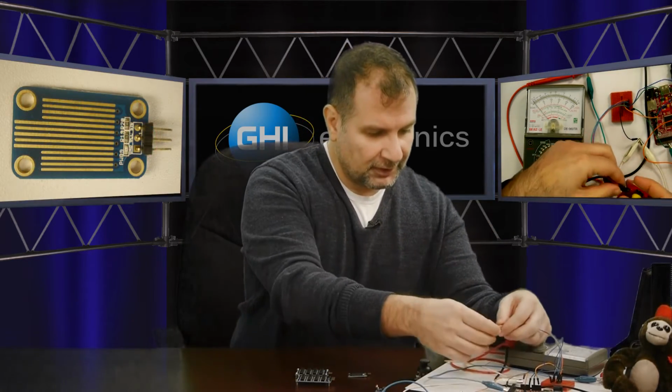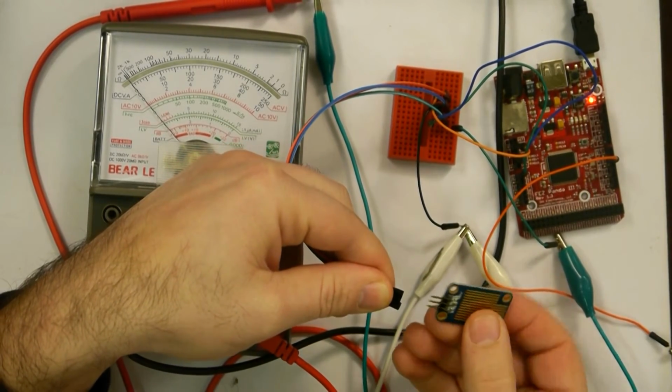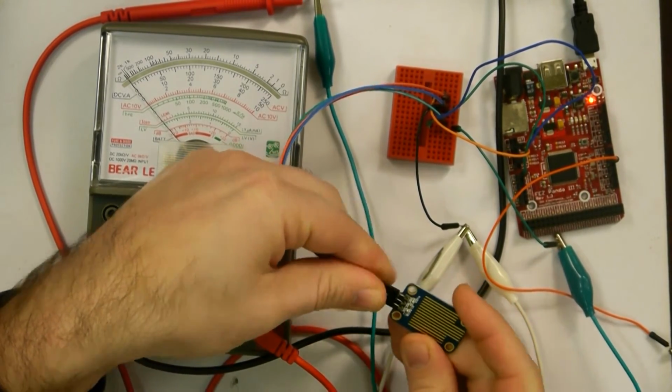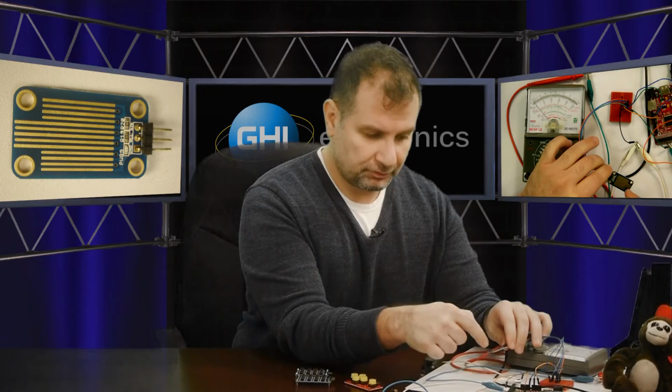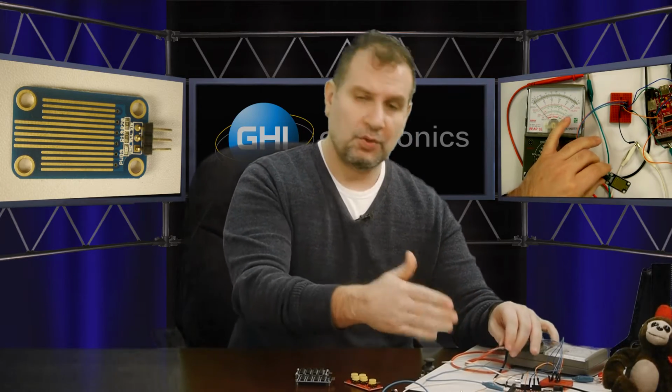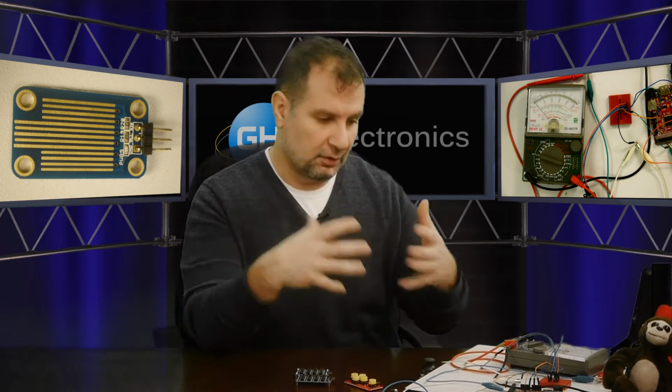Different example over here. I also have a moisture sensor, and this is extremely basic. All it really is, is a bunch of traces, and they are alternating. Every other trace is connected to a resistor, and every other trace is going to ground. And then when moisture, or something conductive, goes between those traces, that changes the overall resistance of the circuit, which changes the voltage.